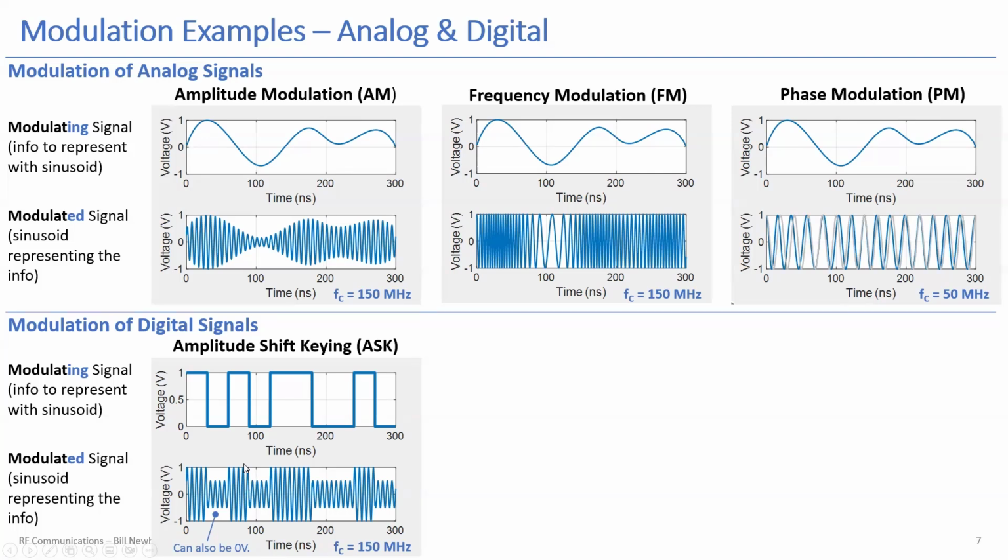If you show this to an expert in communication systems, they're going to say that digital waveform shouldn't really be perfectly square like that. Usually we shape the modulating signal so we don't have these sharp transitions, because sharp transitions in a modulated waveform actually occupy a wider bandwidth unnecessarily. We're not going to worry about that now.